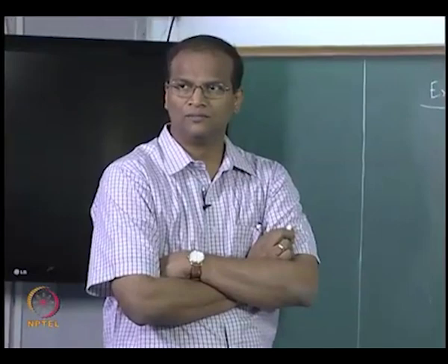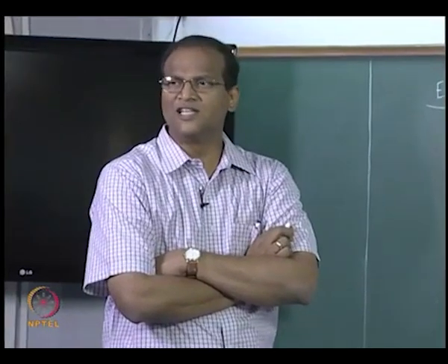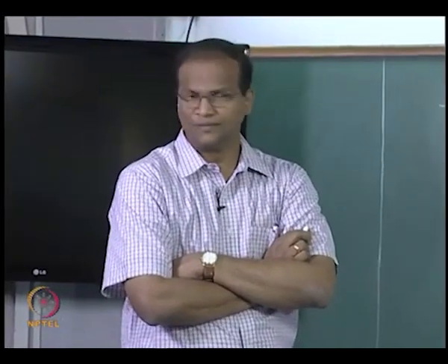So it is a waste of time to get F21, F22 and all that. Whenever you have surroundings like this, do not waste time in calculating those view factors.